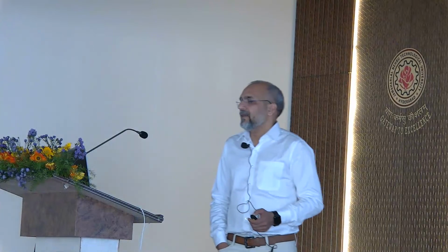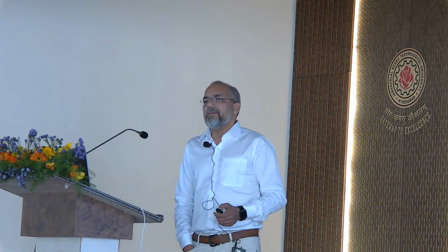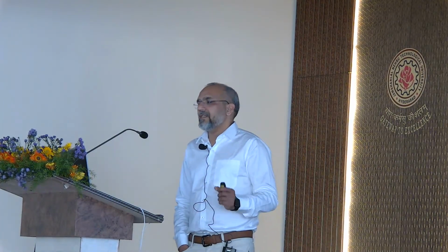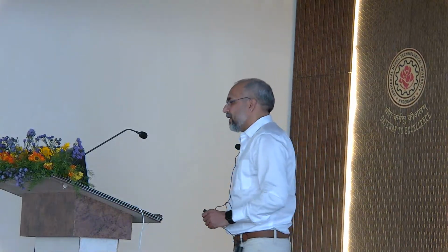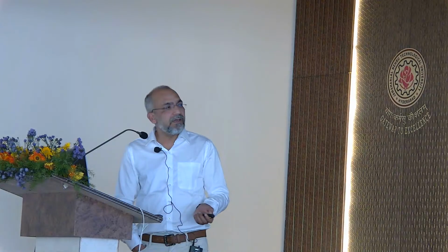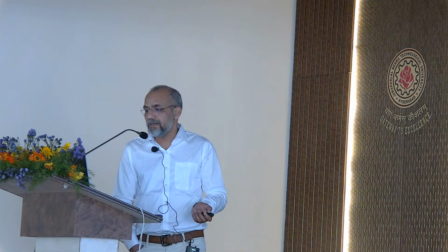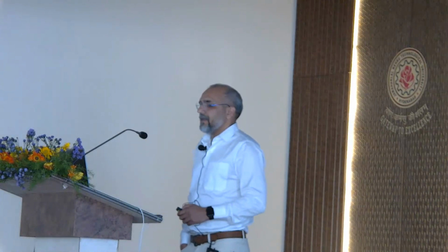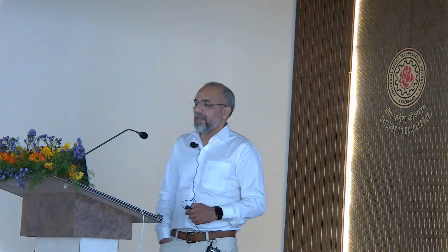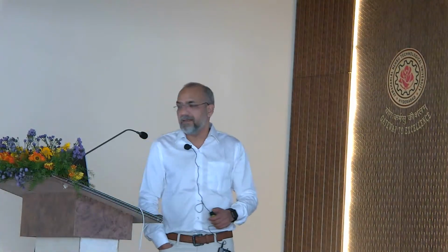The first is the top-down approach and ball milling. As I mentioned, it looks very straightforward. You have bulk material, simply crush that bulk material, and finally find the fine powder. But there are different steps, different stages. It goes from squeezing stage, then grinding stage, then fracturing, and then segmentation of flattened particles, and at the end of the day you will have this fine powder. That is the dynamic balance stage.